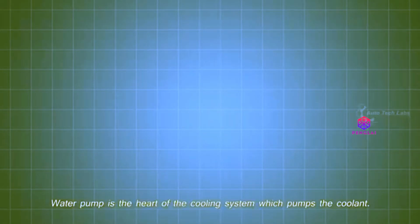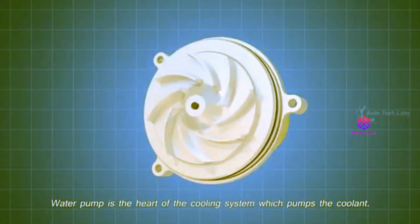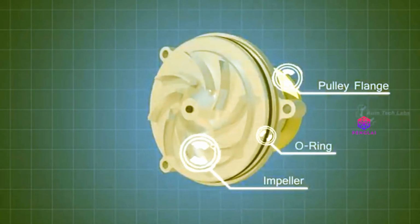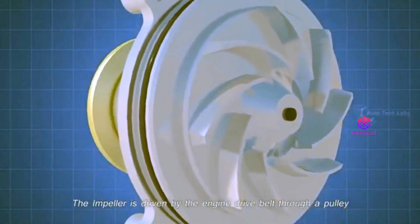First, the water pump. The water pump is the heart of the cooling system, which pumps the coolant. It consists of an impeller, a pulley flange, and an O-ring. The impeller is driven by the engine drive belt, through a pulley.